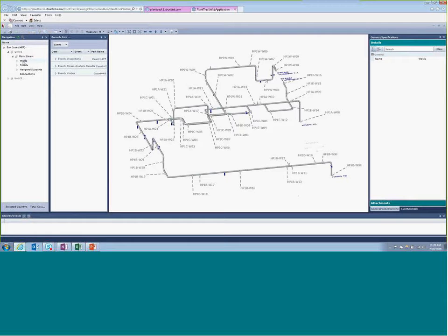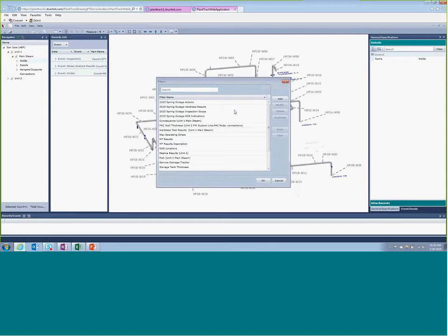It's a safety aspect. So the index and the consequence gives you the overall risk profile, which is a score from 0 to 100. So go ahead and I'm going to run one of these filters. It's going to give you a graphical display. So say we've come in and we've done this assessment and we've generated a risk profile. So we're going to look particularly at the welds.